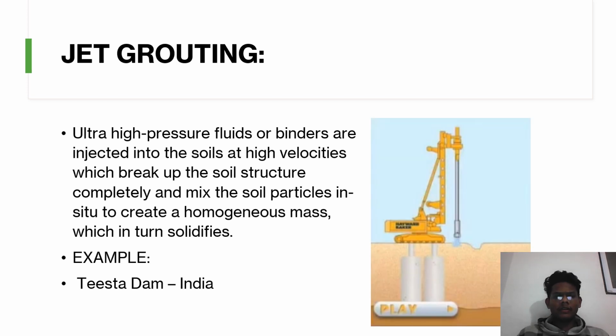What is jet grouting? Ultra high pressure fluid or binders are injected into the soil at very high velocities, which break up the soil structure completely and mix the soil particles in situ to create a homogeneous mass which solidifies. For example, Tehri Dam.